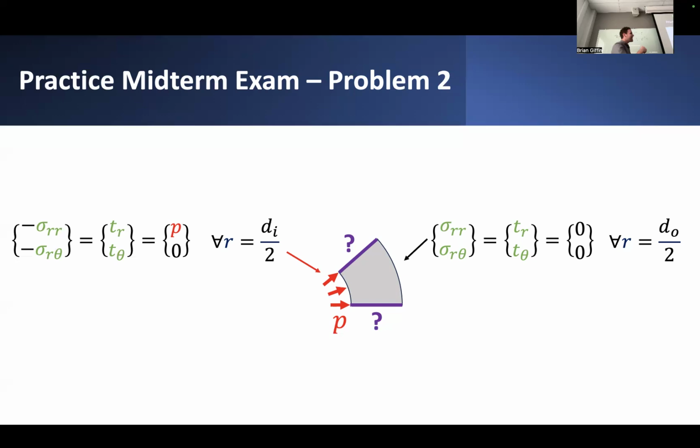I partially agree. What we want to have happen is that if, let's say, we have this cylinder, well, in practice, what do you think is going to happen to this cylinder if we impose an internal pressure load? Just conceive of it in your mind and then describe visually what would happen. Yeah, it would expand. The whole thing would expand out in the radial direction. So a point that was originally here is going to displace purely in the radial direction. It really shouldn't exhibit any displacement along the circumferential direction.